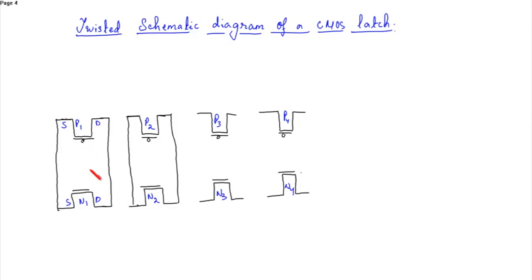The gate will be connected like this. And from here, for showing the schematic, we could have done it directly, but from here we can have an idea to draw the layout. So we have to draw the schematic in a way we are drawing the layout.